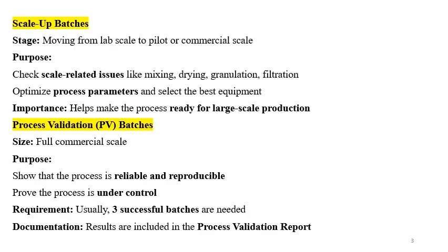Then scale up batches. This is the stage moving from lab to pilot scale. Purpose is to check the scale related issues like problems in the mixing, drying, granulation, filtration, depending on the formulation design, and also to make the process feasible, to study the feasibility at the scale up batches.